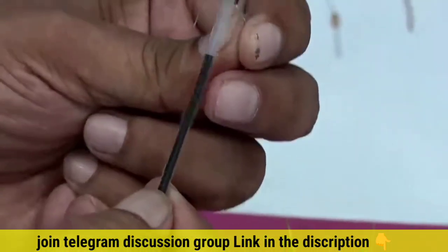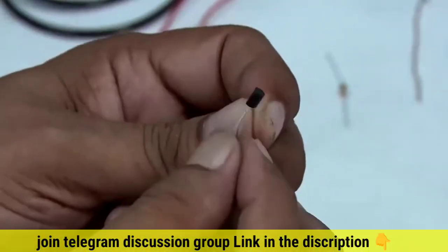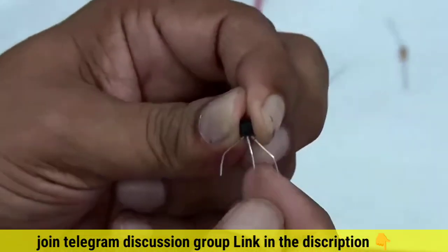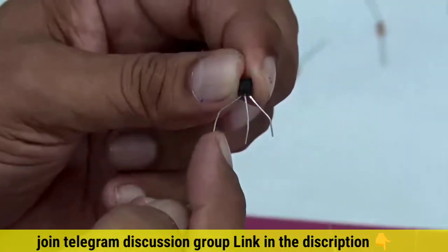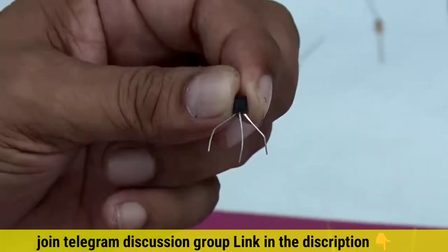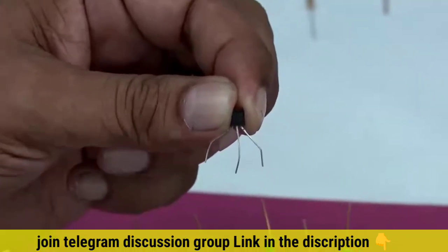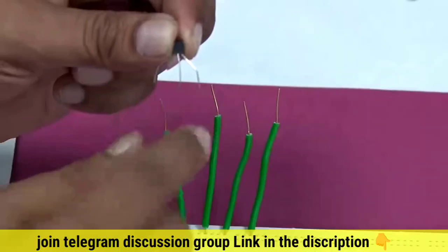So, keep the flat part towards yourself. Then what is on the left is the collector, what is on the right is the emitter, and what is in the middle is the base. So this is collector on the left, emitter on the right, and base in the middle. We will be connecting this transistor into the breadboard in 3 different lines. They do not have to be connected to each other, so they will be connected in 3 different lines.